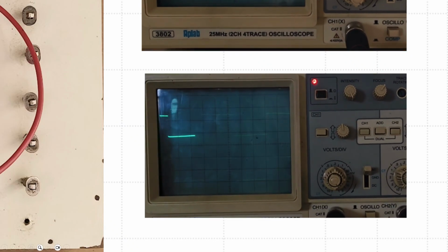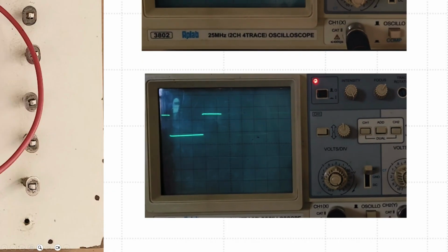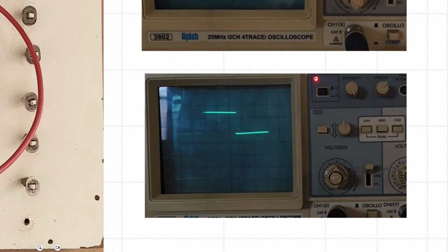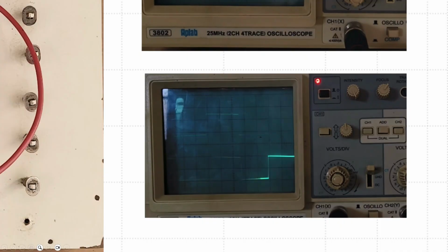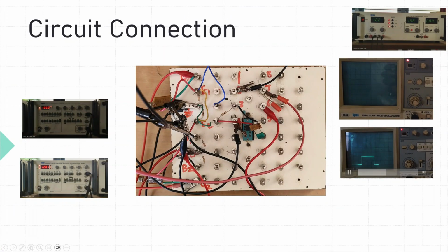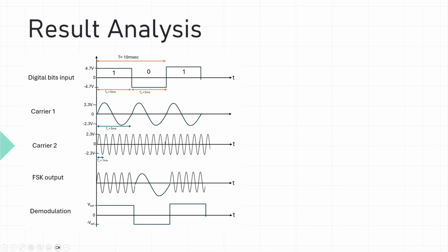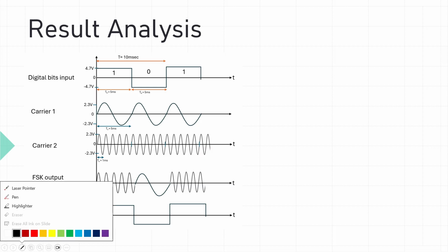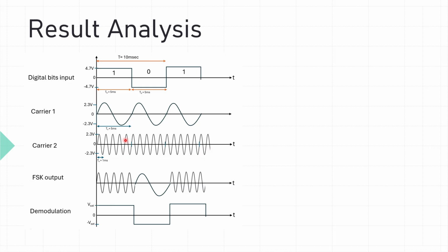As usual, you measure the on time of this and the total T, find the duty cycle, find the error, and find the frequency of the message signal recovered. So this is the waveform that you can write for frequency shift keying.